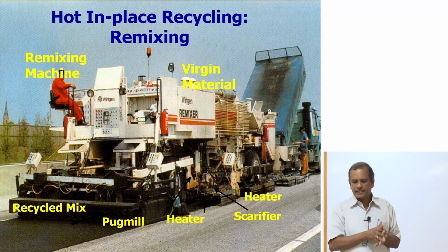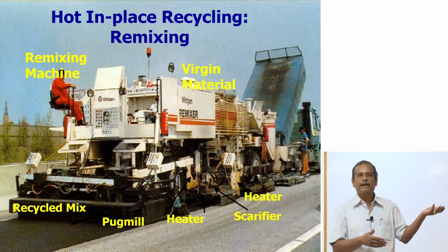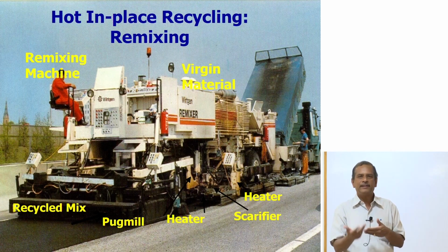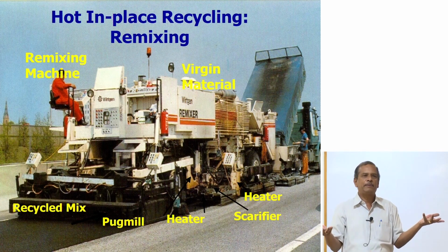So the technologies that have to be adopted in the years to come are, number one, you have to reduce the construction, either by stabilizing the subgrade using geocells, geogrids, geosynthetics, using modified binders, or in the case of recycling, adopt white topping, or recycle the material, either hot recycling or cold recycling. Any of the technologies can be adopted.